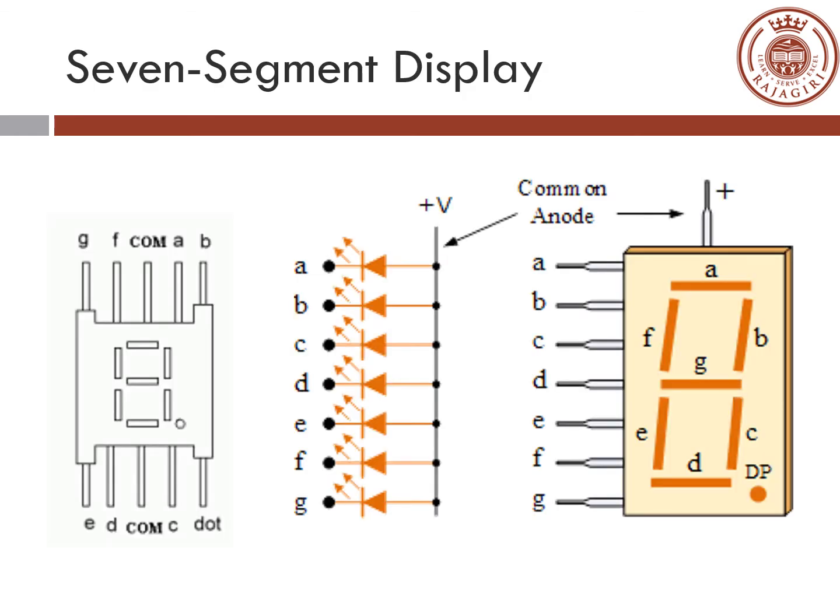Now we will look at the 7-segment LED display and how to build a scanned multiplexed display using 7-segment LEDs. On the right hand side, we can see a 7-segment LED display package. So we have 7 segments numbered A, B, C, D, E, F in the clockwise direction and a segment G in the center, which can be lit as required to display the characters.